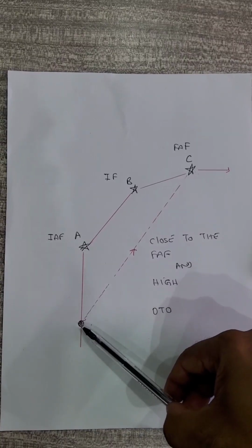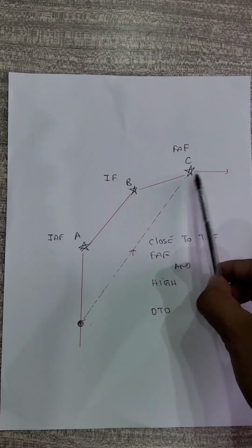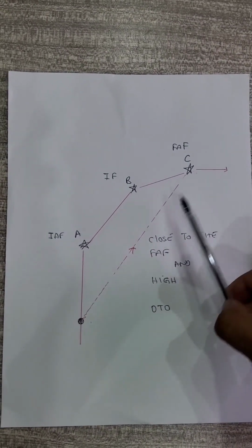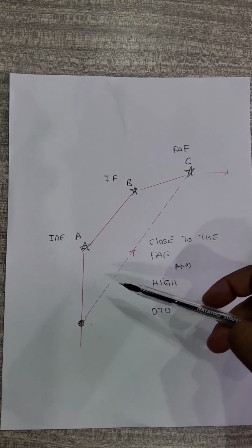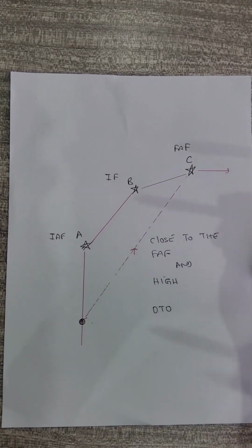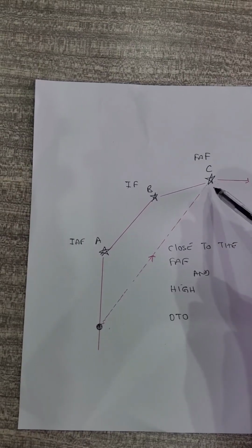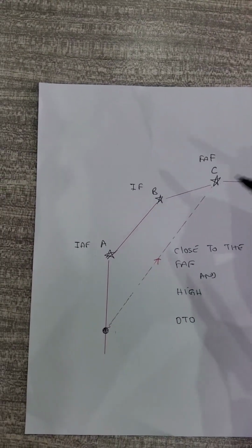Now you want to go from here, where it was initially going there and there and there, straight from here to there. That is a very big vertical distance that the FMS has to accommodate, and to do that it will command the autopilot to dive, so we go there, and that's not what we want. We do not want the FMS to dive. So what do we do?